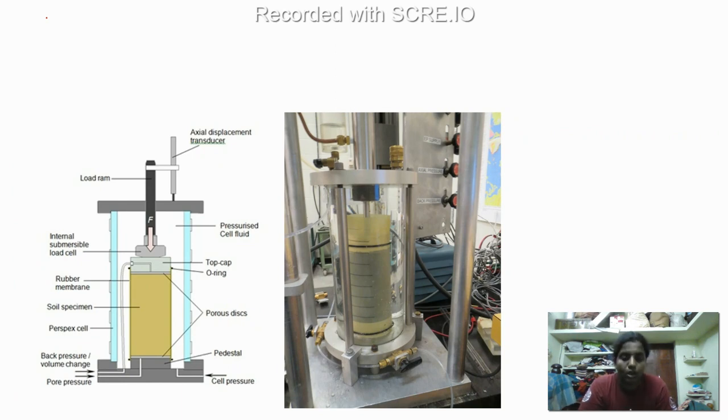In triaxial, or even there is one more permeability I can say, called flexible wall permeability, similar to what we conduct in a triaxial setup. In triaxial, when we are going to conduct the test for clay soil, we have to ensure that it is 100% saturated. Even though you keep the soil in water for 24 hours or whatever, your clay will not be 100% saturated. You will be able to attain only approximately 95% degree of saturation.